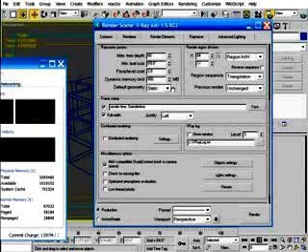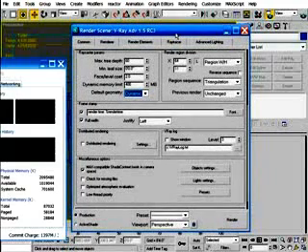In a nutshell, VRay gathers a lot of information about objects in a scene, and it performs an immense number of calculations based on the information it gathers. When objects are treated as static geometry, the information it gathers is kept in RAM until the entire rendering process has been completed. And for large scenes, this can often result in Max crashing, as it did here. When objects are treated as dynamic geometry, the information VRay gathers is continuously compiled, used, and then discarded. And this allows you to render very large scenes without running out of RAM.